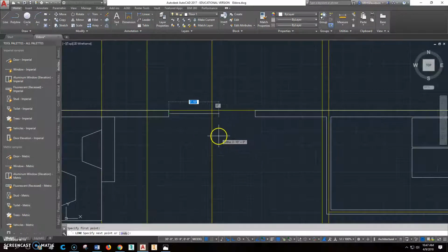So we'll come out here. So instead of going 40 inches, we'll make it go 42 inches. And I'm going to, since the wall thickness is 6 inches, we're at the 3-inch mark. I'm going to move this one down, out this way. I'll move it out 1 inch that way.